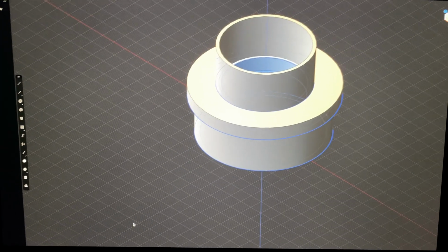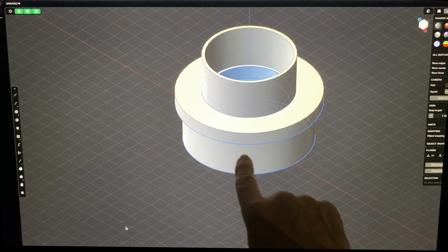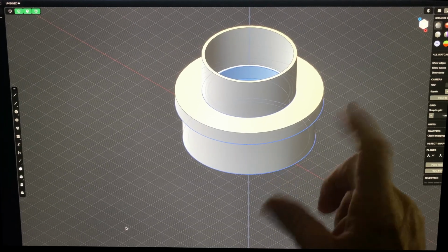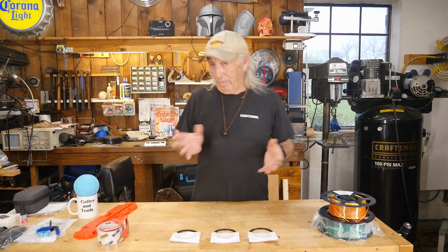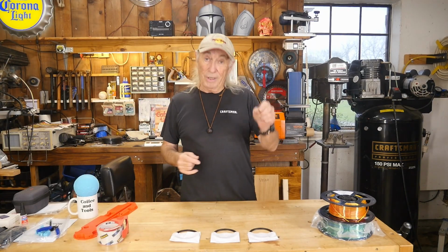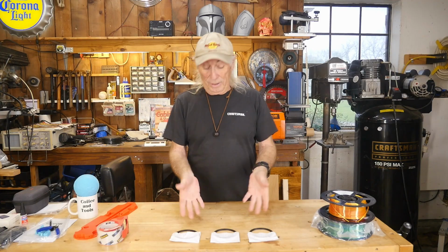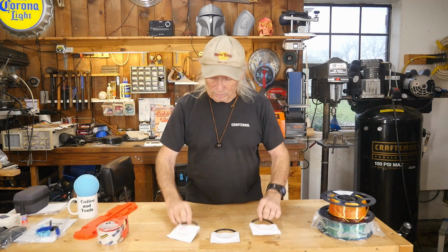And you see how for a second there it flashed on the screen with really tiny lines, because now all the little triangles, which is part of drawing up in CAD and converting to G-code and things, is much better, a much smoother model, much rounder. Yeah, so you saw it right there. Just change that density setting and bang, you'll have nice round rings or rounded corners without flat spotting.